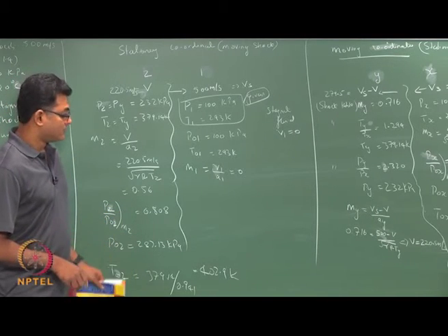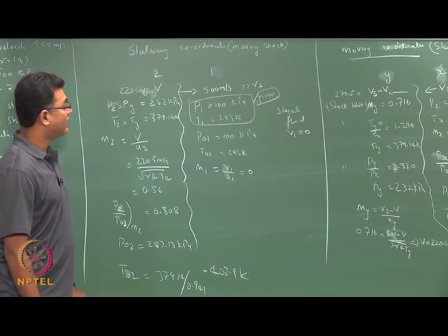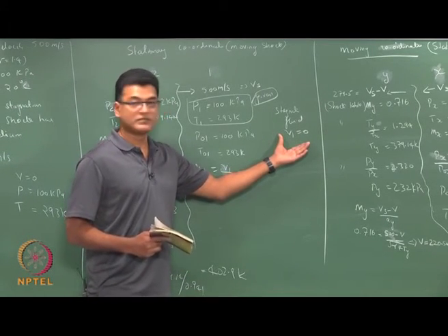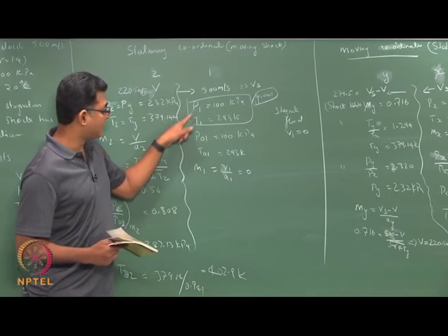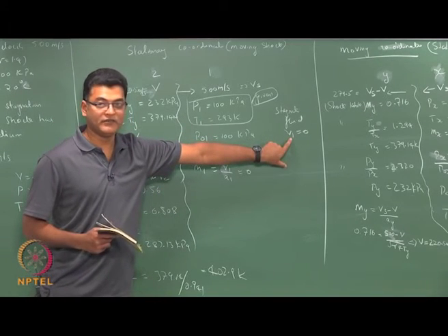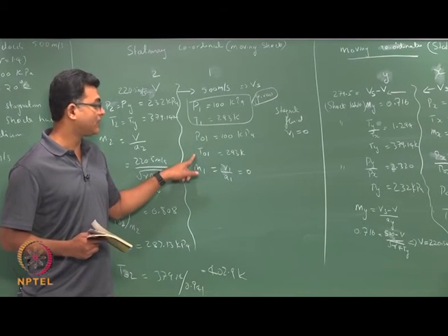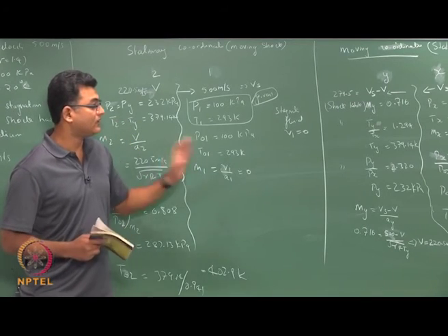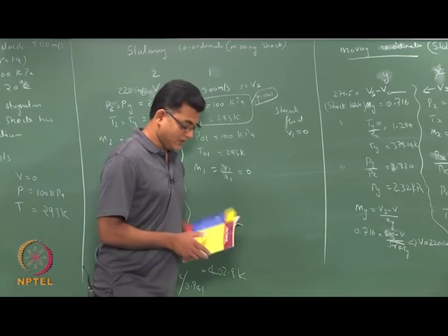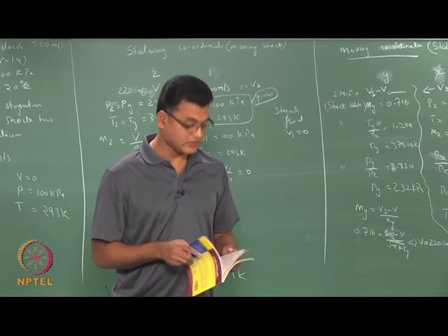Okay. So with this I think you can do any kind of problem, even when the V here is not stationary, except that you cannot equate P01 equals P1. Okay. So if you have a finite velocity here, then P1 and P01 cannot be equated, and T1 and T01 cannot be equated, otherwise everything is the same. Okay. So that brings a small discussion on moving shock.